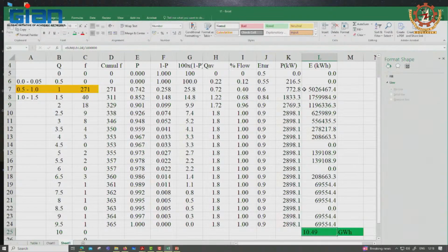Therefore, you can further increase the total by optimally operating the two turbines and accordingly reflecting that in this Excel sheet, rather than saying we take one turbine until it is fully loaded, and then load the rest of the water from the beginning onto the other one. That is not the actual way of doing it.